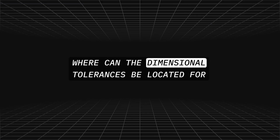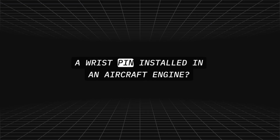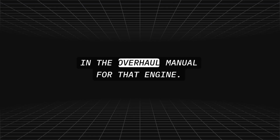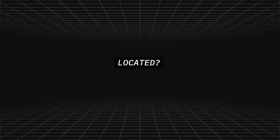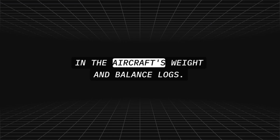Where can the dimensional tolerances be located for a wrist pin installed in an aircraft engine? In the overhaul manual for that engine. Where can the empty weight of an airplane be located? In the aircraft's weight and balance logs.